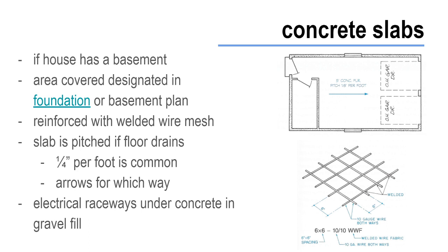You'll see that a lot in big warehouses. If I was walking around a Costco, you can look at the floor and see where there's that little piece of expandable joint, so that as it expands and contracts, it's not going to crack.